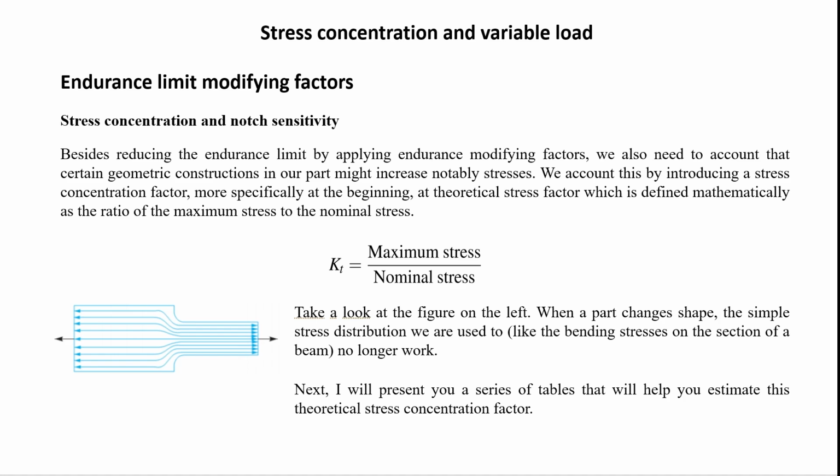There is another element we need to consider in fatigue design, and that is stress concentration. Stress concentration is included in fatigue design using a parameter called notch sensitivity. We're going to see how to calculate it, but there are books dedicated to stress concentration factors. One of the most famous books for this is the Peterson Stress Concentration Factors book.